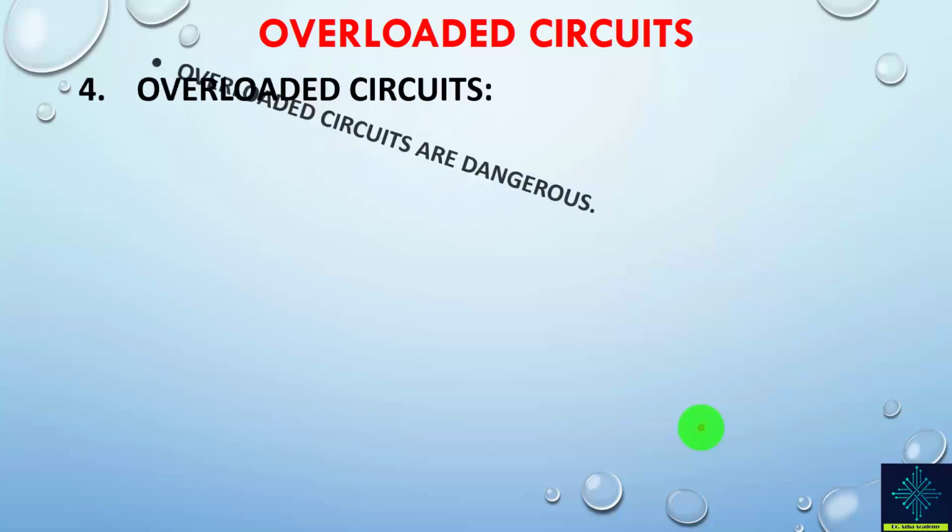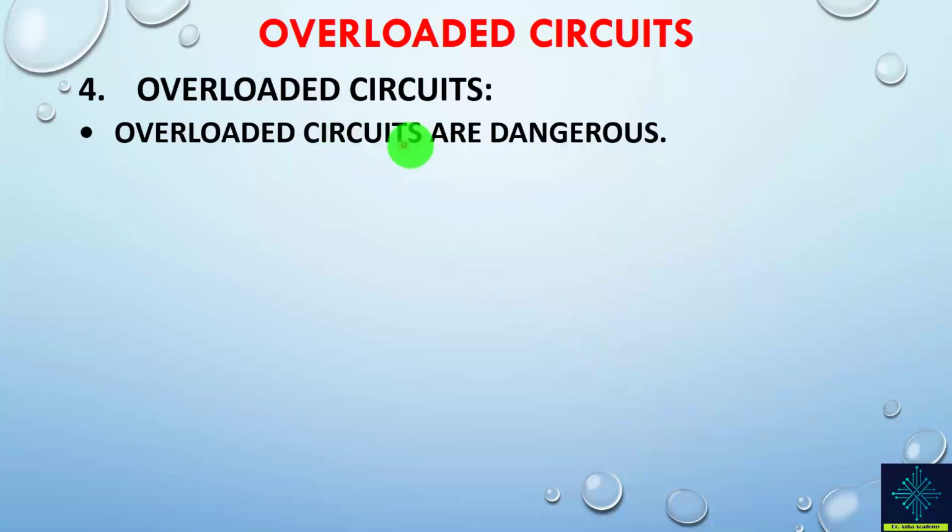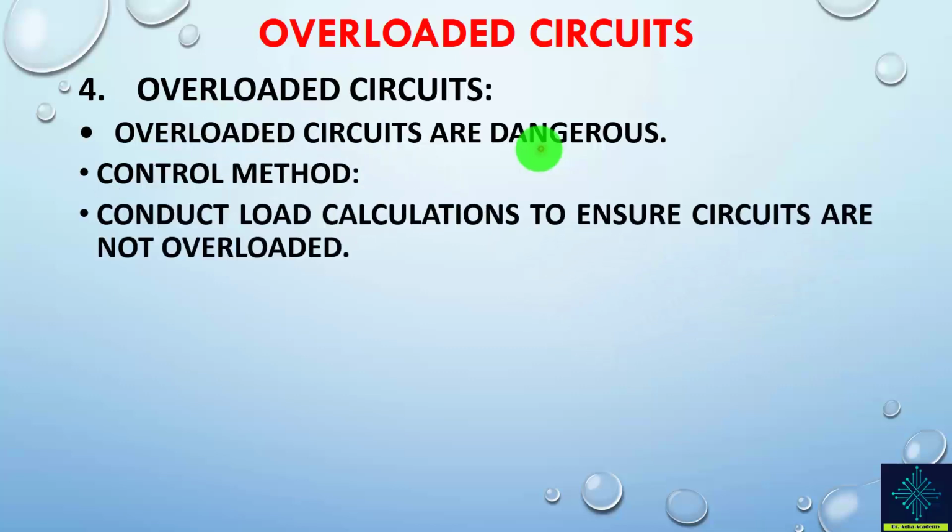Overloaded circuits. This is again a hazard. Overloaded circuits are dangerous. I've seen such circuits leading to fires and serious injuries and sometimes fatalities. The control method includes conducting load calculations to ensure circuits are not overloaded.